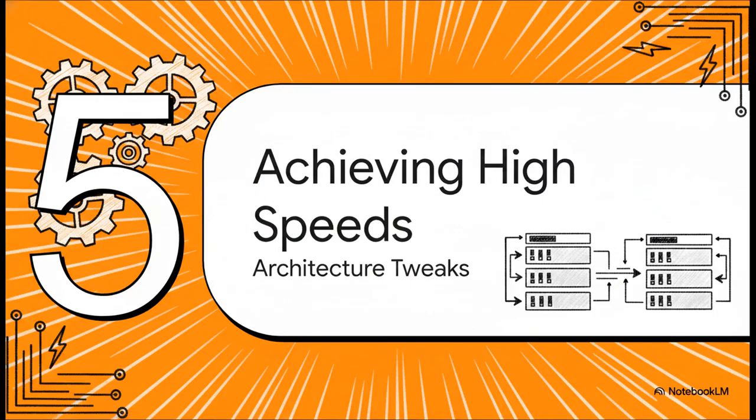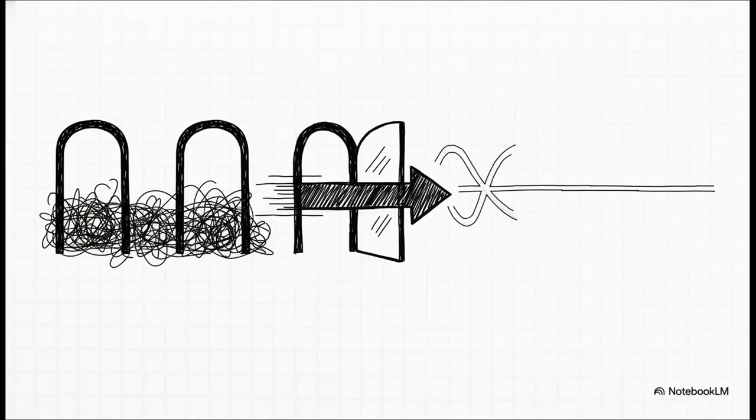Finally, Section 5, Achieving Incredible Speeds Through Architectural Optimizations. Let's see how engineers overcome these delays to make DRAM so incredibly fast. Engineers use a few brilliant tricks here. First, row hits. If a row is already open, the logic skips the pre-charge steps completely. This is exactly why we use 32 independent banks, so multiple rows can stay open. Also, we break massive grids down into 1024 by 1024 sub-subarrays to shorten the physical wires and reduce resistance. We even use cross-coupled inverters to actively cancel out electrical noise. Top-tier logic design right there.